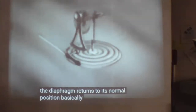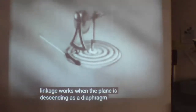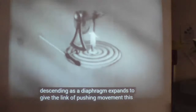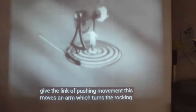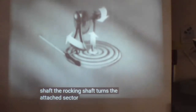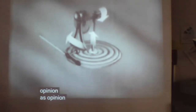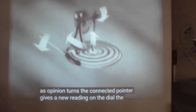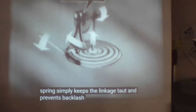Basically, here's how the mechanism works when a plane is descending. As the diaphragm expands, it gives the leg a pushing movement. This moves an arm, which turns the locking shaft. The locking shaft turns the attached sector, which is meshed with the pinion. As the pinion turns, the connected wire gives a new reading on the dial. The airspring simply keeps the linkage taut and prevents backlash.